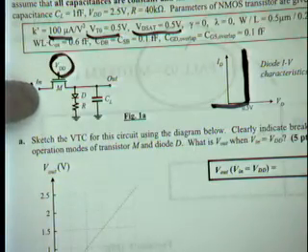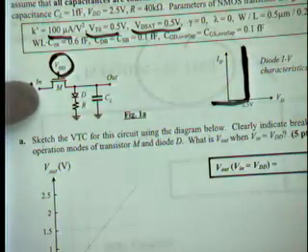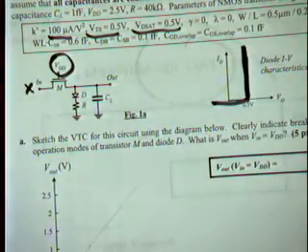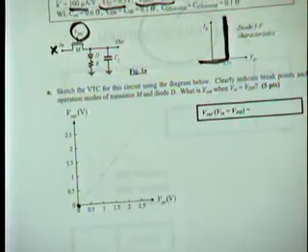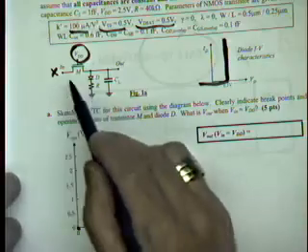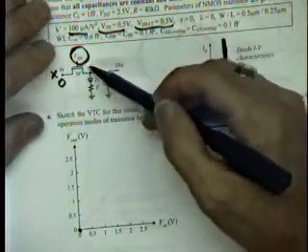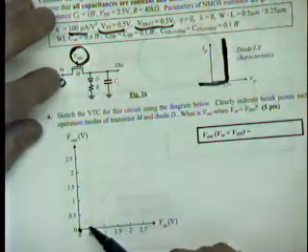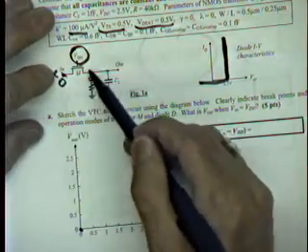If you make the input 0 here, what do you think is going to happen with this diode at the output during that time? So basically at this point V in equals 0. What do you think the diode is going to be in? Just a rough sense. It's going to be off, right? I personally cannot see any way that diode can be on. You have to have that 0.5 volt from somewhere. So my input is 0, the diode is off, so we're just going to couple the input to the output. This device is on, so this node is going to be equal to this node.